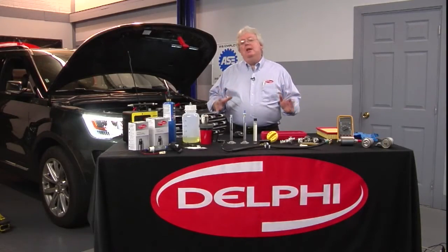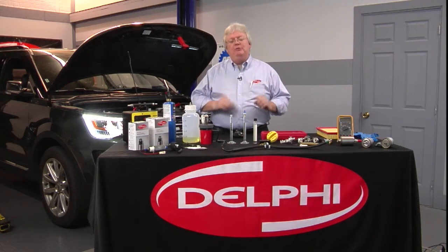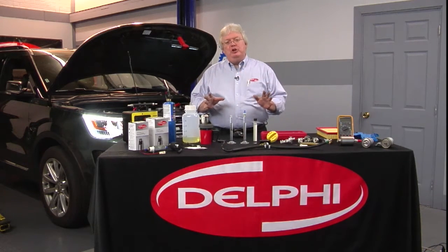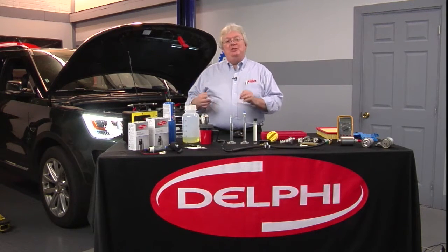Now, let's do the on-car demo on that vehicle I was just talking about. Working with a late model Ford non-gas direct injection, so it's got regular sequential fuel injection, no turbocharger, and no mass airflow. So it's speed density looking at the MAP sensor only.